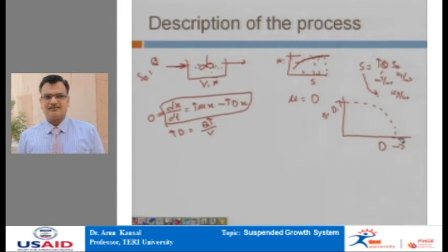So, the entire discussion I am repeating again in this context: first of all, we have to increase the microbial population in the aeration tank. To increase the microbial population, we have to increase the supply of food. The concentration of BOD in the wastewater is more or less constant, so we have to increase the discharge rate for a given volume. By doing so, though we are giving microorganisms the opportunity to grow, we are also giving more dilution. The net effect is that there is no net growth of microorganisms, but rather after some stage there will be washout.